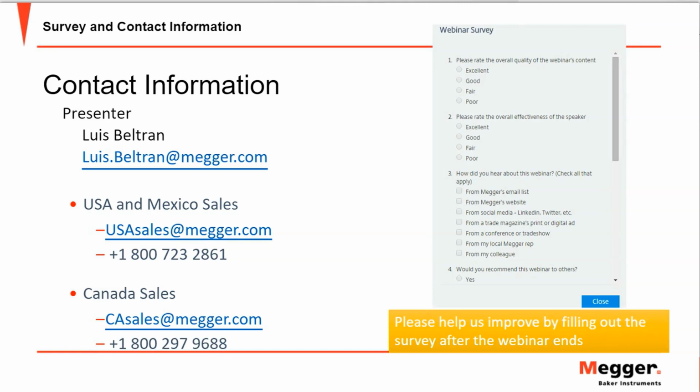As I said, there's no standard for the ER percentage. It's our invention, it's our patent, now improved, but our recommendation is between 5 and 10%. So the key of this information is the trending. So if we are testing a motor for the very first time and I have 10%, so it's something that I think I need to think about.